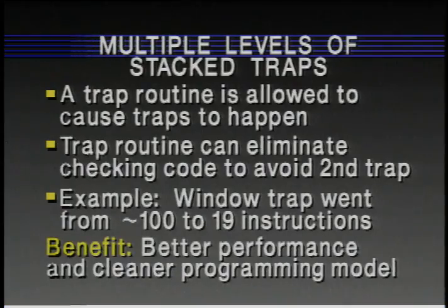An error can still occur, but then you'll trap to a different routine which can handle the abnormal condition and recover. Almost all the time, in fact, these abnormal conditions will not occur. So again, we're taking advantage of the RISC paradigm of supporting the most common condition very, very quickly and allowing abnormal conditions to be handled in software. The real benefit to us is going to be overall performance gains and a much cleaner programming model as well.